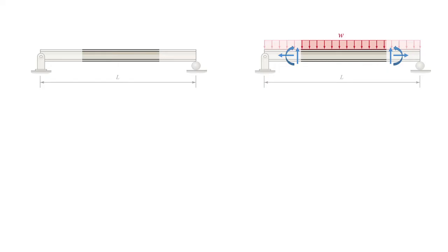Axial force is already discussed in the axially loaded elements. In beams, we are typically interested in shear force and bending moment. And in this lecture, we want to learn how to construct shear and moment diagrams in a beam. Different methods could be used for constructing shear and moment diagrams. Here we are going to talk about the graphical method, which is a relatively simple method for constructing shear and moment diagrams.